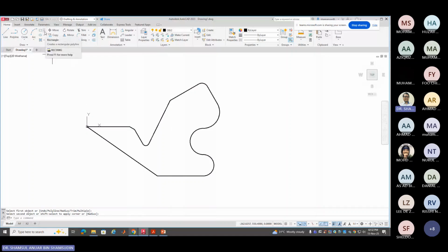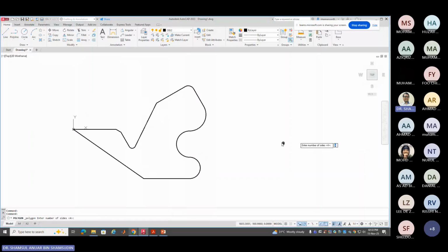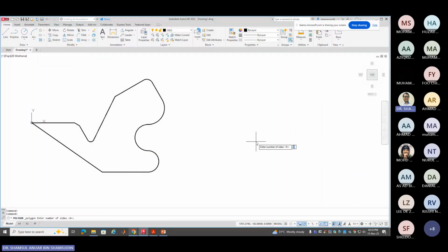We can add maybe, I guess one thing I have not utilized is polygon. Here, polygon, there are many types of polygons, many ways to do polygons. So, for example, six-sided is a hexagon. So we type in the number of sides 6, hit enter, specify polygon.